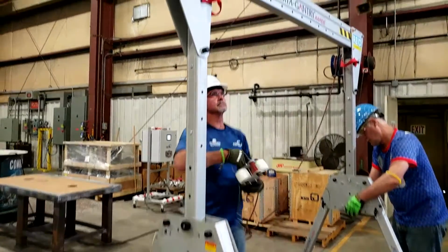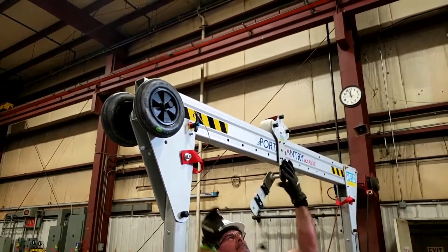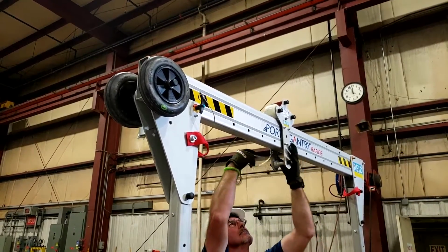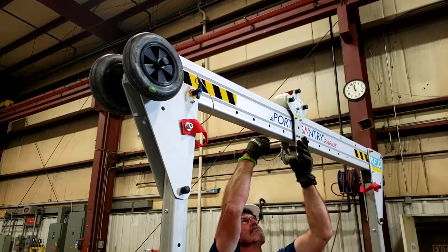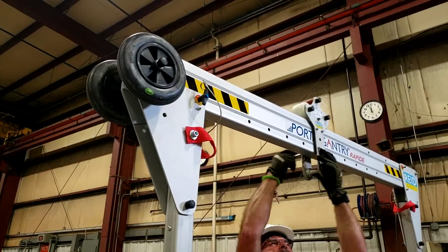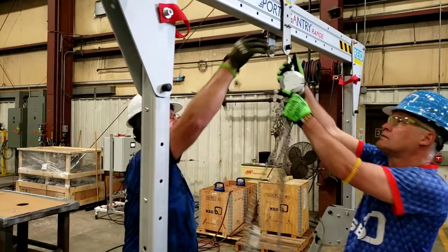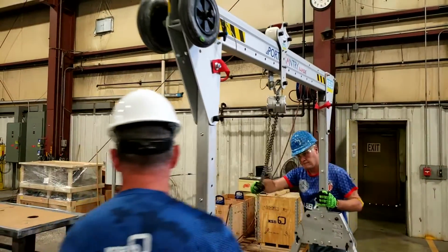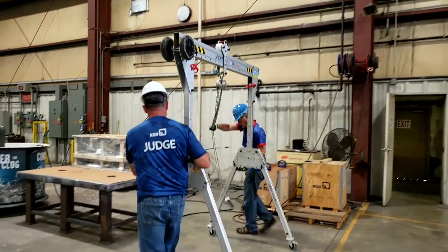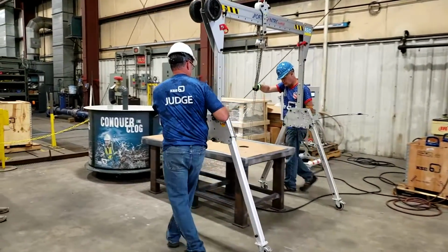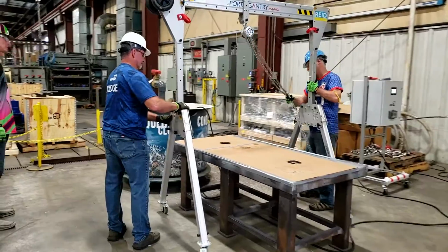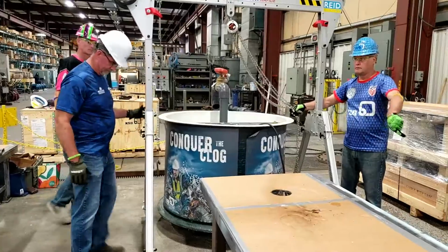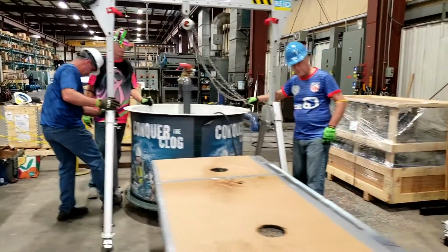With the gantry fully assembled and set up, you will now install the trolley and chain hoist. The trolley shall be installed in one of the 3 center holes of the gantry unit. Once the trolley has been installed and pinned, you will then install a chain hoist by hanging it from the trolley. You are now ready to position the gantry over the wet well. This requires the use of a minimum of 2 people, 1 on each leg of the gantry. Once you are in place over the wet well, you will lock all 4 gantry wheels.